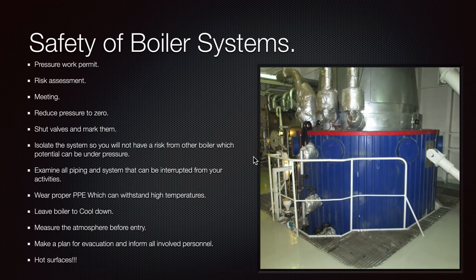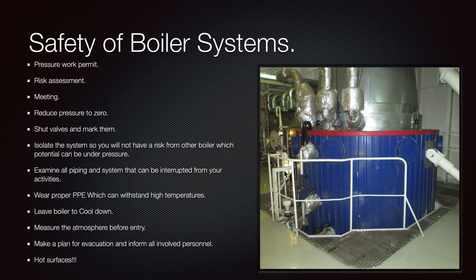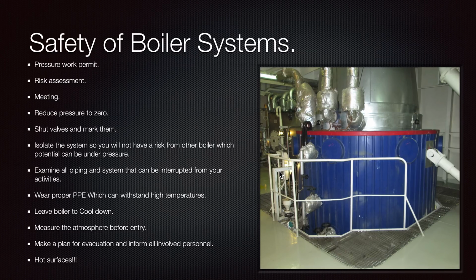Always, before you enter the boiler, measure the atmosphere, and the people involved there should have portable monitors that are always monitoring the atmosphere inside. Always make measurements and always make an enclosed space entry permit.